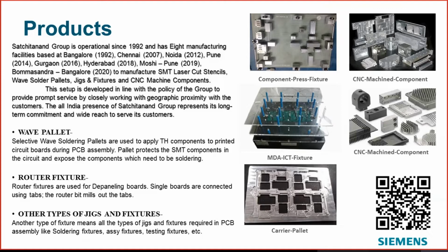MDA ICT is used for testing of PCBs, whether the components, the resistors, capacitors are as per the value indicated in the BOM file and whether the circuit is working as per the spec. The carrier palette that you see on the screen is used for the solder paste printing of PCBs in the SMT process. So it's a completely automated line, and over there fixtures are used to communicate between individual PCB boards and the robots.